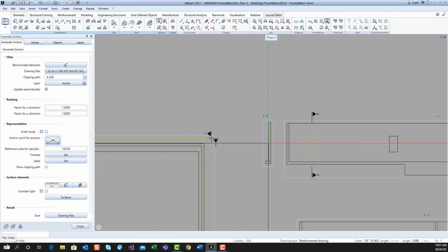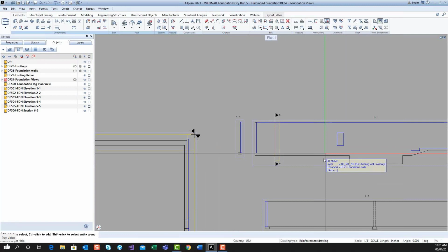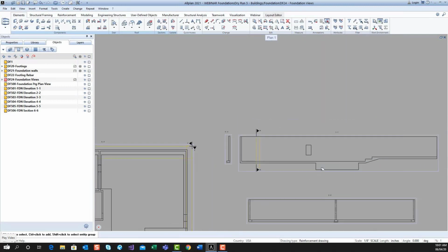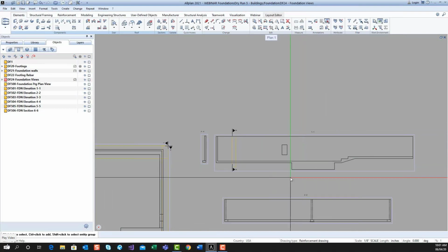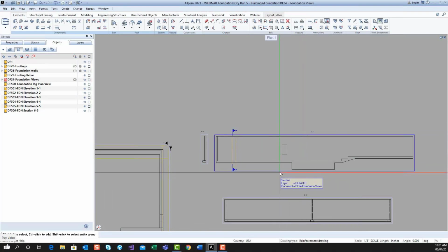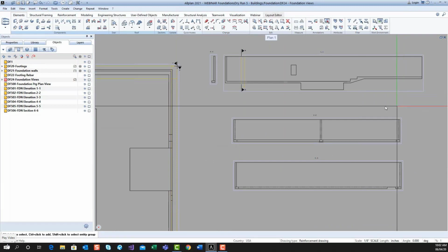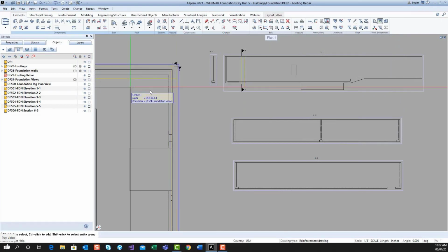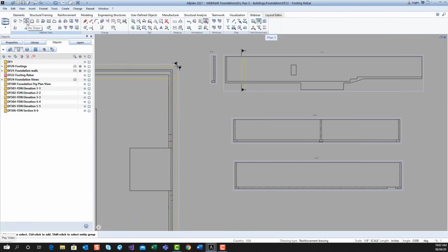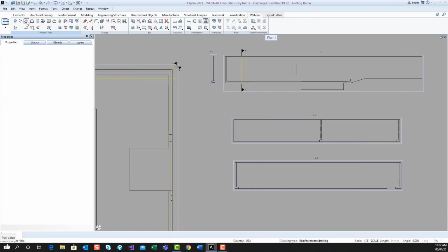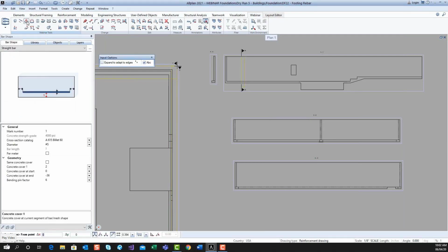With the rebar, we place it similar to what you're used to, through our quote unquote manual technique. And with our manual technique, you're going to see our enhancement tools for putting in rebar. By shaping in one view and placing in another, it's going to appear in whatever views I place it in, as well as in the 3D model. And we're going to use our existing line work on our quote unquote concrete to apply covers and so on. In this next area, we're going to apply some longitudinal bars in the bottom of our footing.